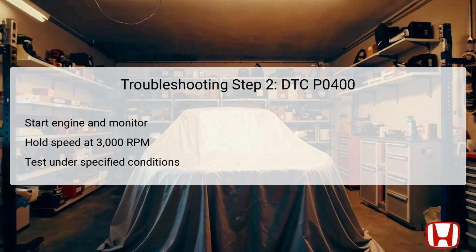After this, a test drive is necessary under defined conditions, ensuring the engine coolant temperature exceeds 158 degrees Fahrenheit or 70 degrees Celsius.